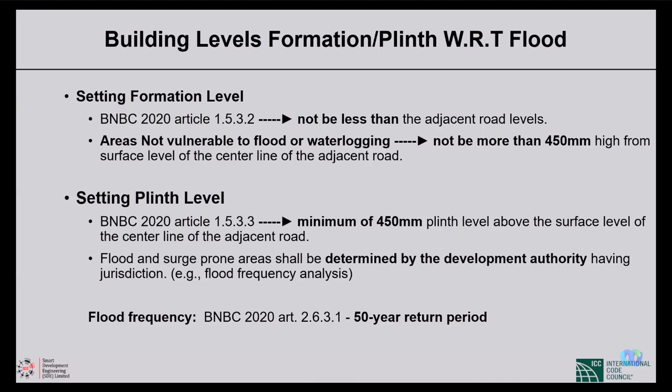Then here are some of the standards. So what we're talking in building levels, formations, and the plinth level. How are you going to put it? The setting of the formation levels according to the BNBC 2020 Article 1.5.3.2, not be less than the adjacent road. So your formation level should not be below the adjacent road. This is one point they said.